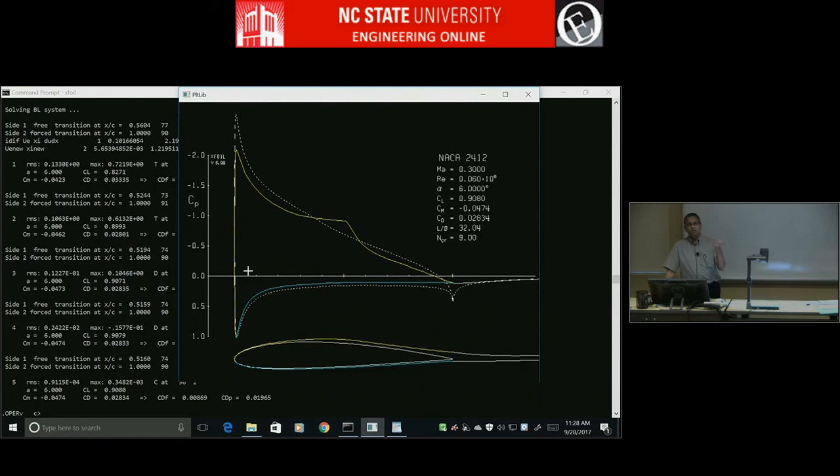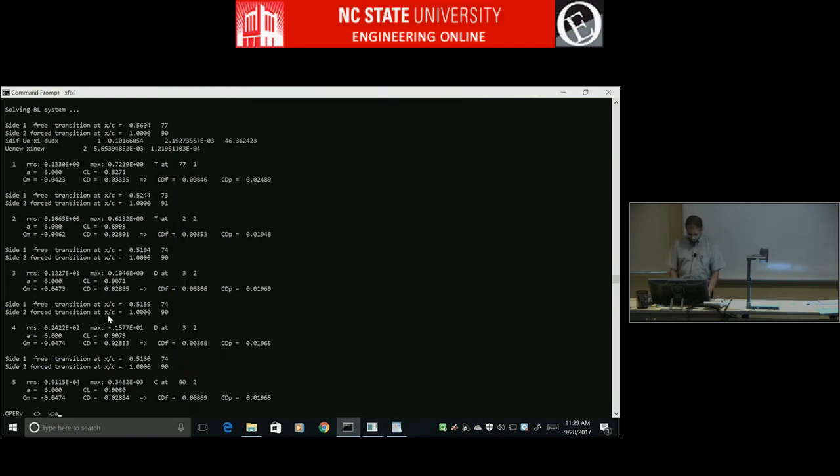Maybe not, maybe it's getting towards that boundary where you should really put the compressibility effects. But usually Mach number up to 0.2, even 0.3, you can get away by simulating it as incompressible flow. After that, you start having to put compressibility effects. You should consider compressibility effects. So let's put something else.